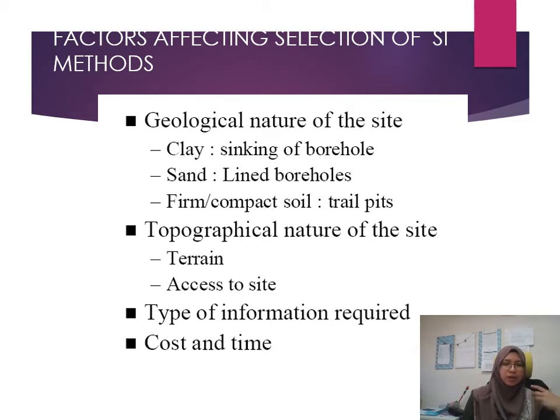If your site is in a swampy area, or in the jungle, the accessibility of the equipment to your site is something that you have to consider, the topographical nature of the site. Can you move that equipment on a hilly site, if you want to go up high? So it depends. You have to select the equipment that suits your topographical nature.